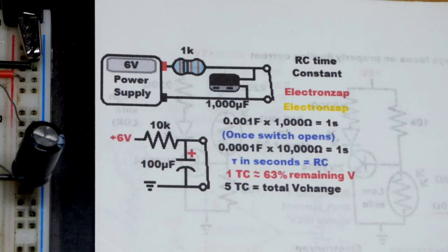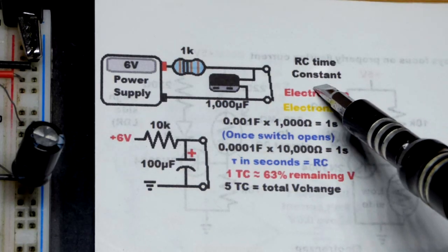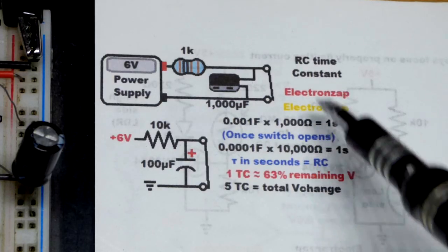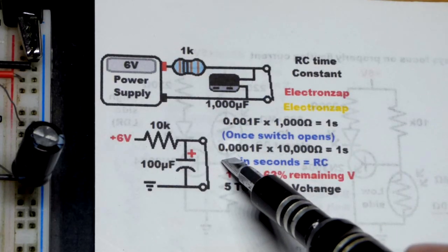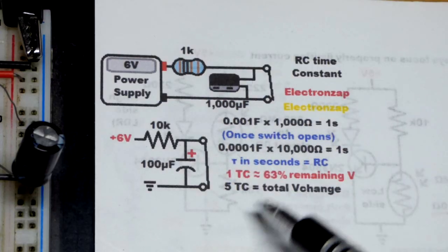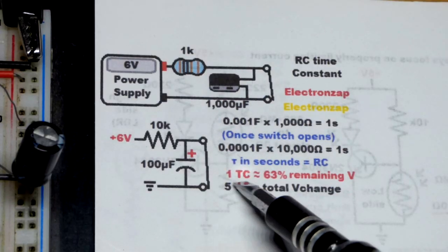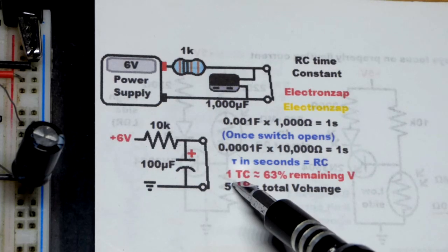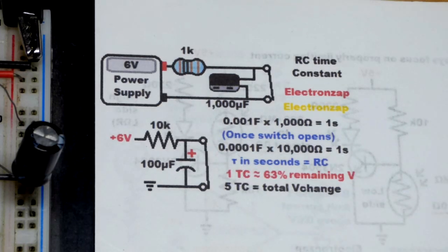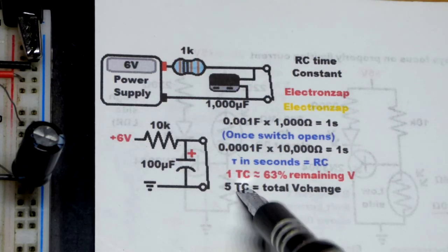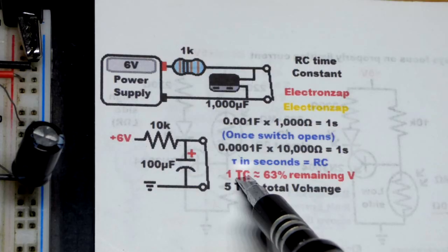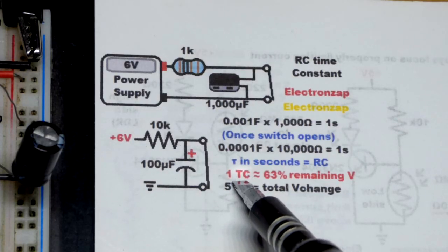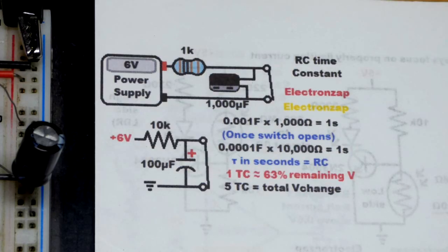So in any case, the RC time constant's used a lot. It's used in the 555 timer, although it jumps between 2/3 of the supply voltage down to 1/3. So that change takes about a second, not exact. Maybe just slightly shorter or something. But that change happens pretty quickly between 2/3 and 1/3, where it gets close to 1 time constant. So not perfectly, but it does a decent job. In any case, I think that's about it.